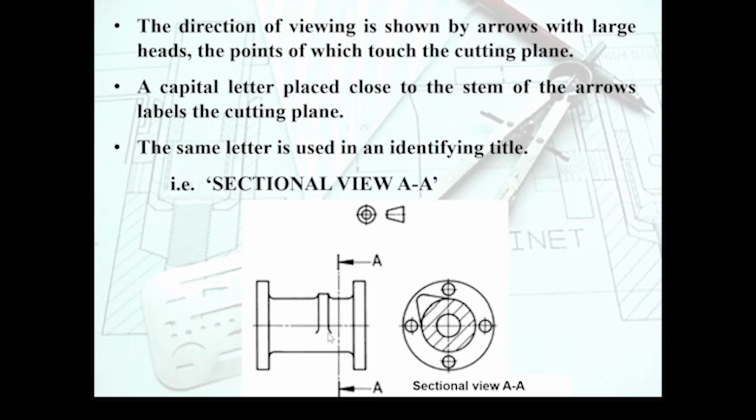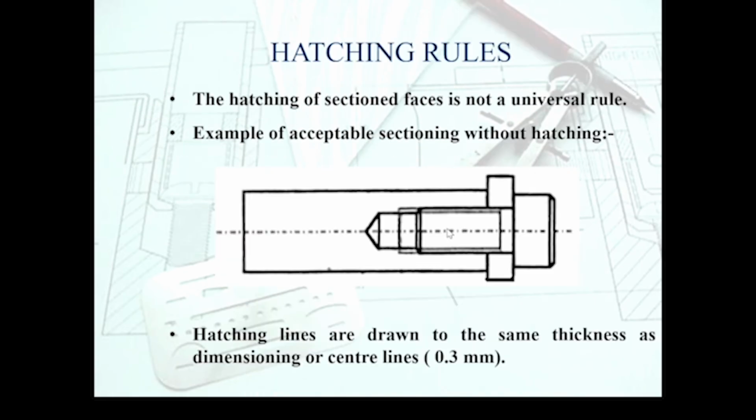This particular view is actually what is left now. So we're going to reveal the inner diameter on the outer diameter, and also that notch is going to be apparent right there, and some mounting holes. I must admit there should have been some hidden details here to indicate these mounting holes onto the right bed. Also, try not to forget to label the drawing as sectional view at AA, because you may have more than one cutting plane on a given drawing. Also follow that with the projection system symbol.